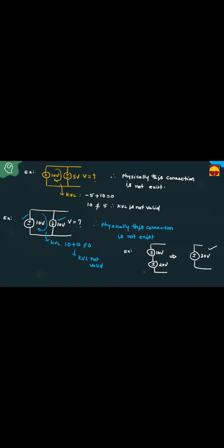Two different voltages you connect in series. For example, if they are given like this: plus minus 20 volts, minus plus 40 volts. Then what is the resultant? Which is greater? Minus plus is greater, so you have to take that polarity. That is 40 minus 20, high minus low, which is 20 volts, but the polarity is minus plus, not plus minus, because only the polarity of the higher voltage should be taken. Like that you have to answer.